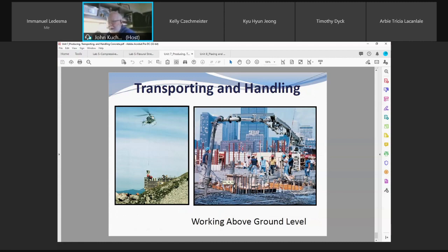The mix that you guys are coming up with, 65, 63, 69% coarse aggregate, would be quite difficult to finish for a nice finished floor slab. It's not enough butter. It's not fatty enough for paste, for finishing, which is what you need for a floor slab. Columns, grade beams, who cares? What do you finish? A 200 millimeter wide top of a grade beam, formed on all three sides other than the top? You can have a harsh mix. You can have probably a 73 mix, which is great.